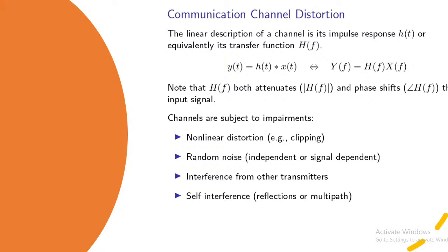So use that principle, take the Fourier transform, and Y(f) will be the multiplication of H(f) and X(f). That is why we usually use Fourier transforms. Instead of doing all these integrations in the convolution, go to the Fourier domain, take the algebraic equations and just multiply them. That is much easier.